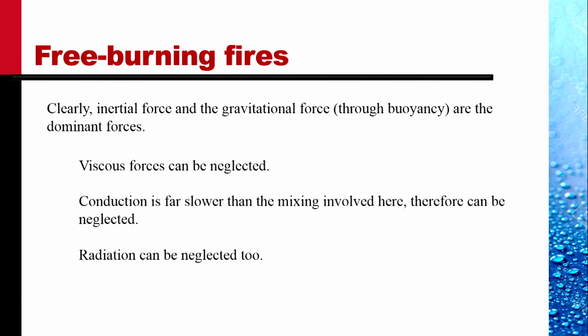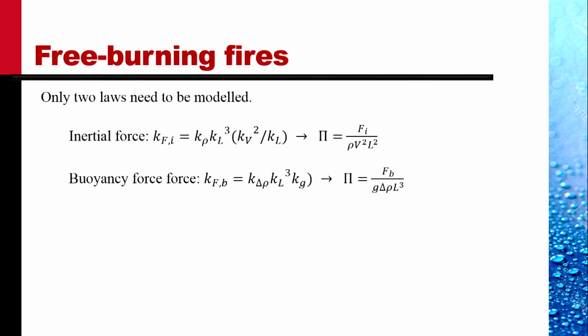Clearly, inertial forces and the gravitational forces through buoyancy are the dominant forces. Viscous forces can be neglected. Conduction is far slower than the mixing of gases involved here. Therefore, conduction can be neglected. Radiation too can be neglected, relatively small energy in radiation. Only two forces need to be modeled.